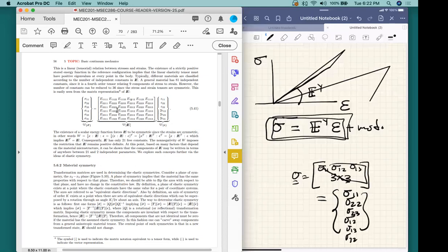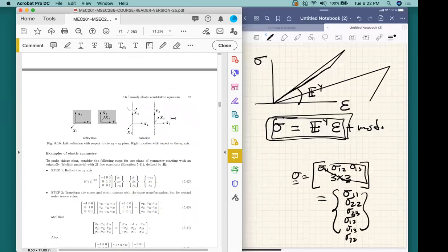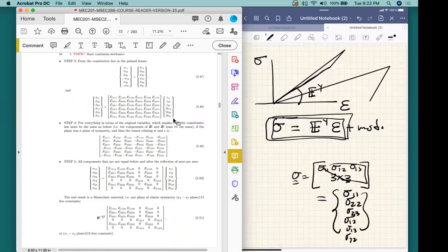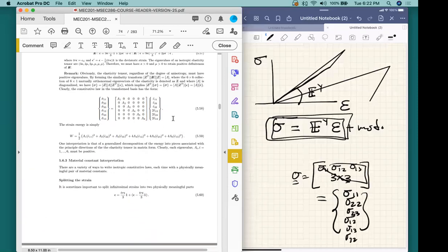So if you're doing very careful analyses of a stress-strain relationship in 3D, you've got to go in there and measure all of these 21 constants. That is not an easy thing to do in the lab. That means you have to have 21 measurements to get 21 constants. So we're going to go through that carefully to figure out how that's done. And we're going to then figure out how to calibrate this material for all kinds of different effects.